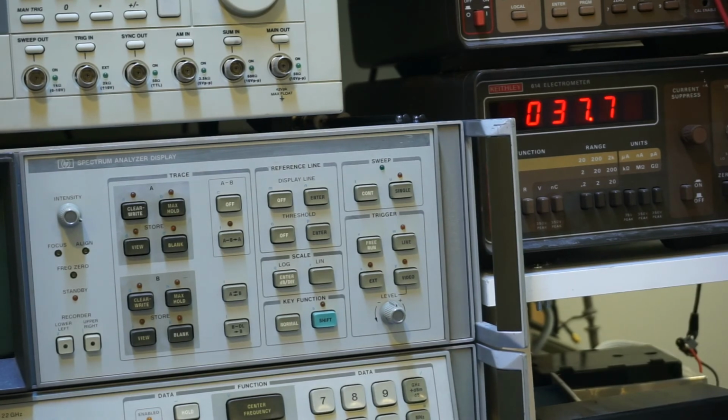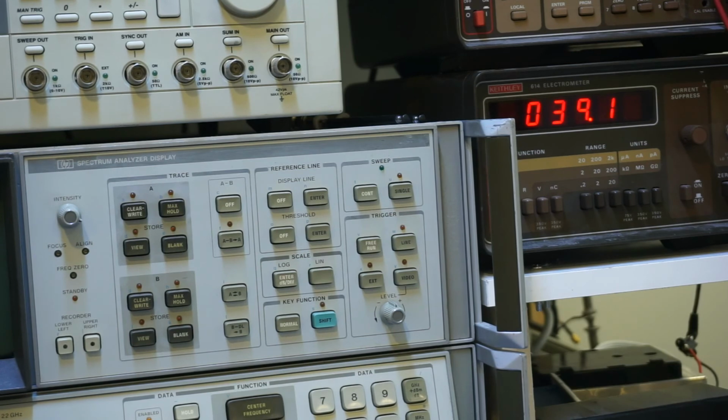So now I'm going to use my flashlight and shine it directly onto the diode. And as you can see, it dropped significantly. Right now it's back to 26, 23. And if I remove the light source, it goes up to 39. So clearly this would have made the results more difficult to characterize. That's why I used a plastic case diode to begin with.